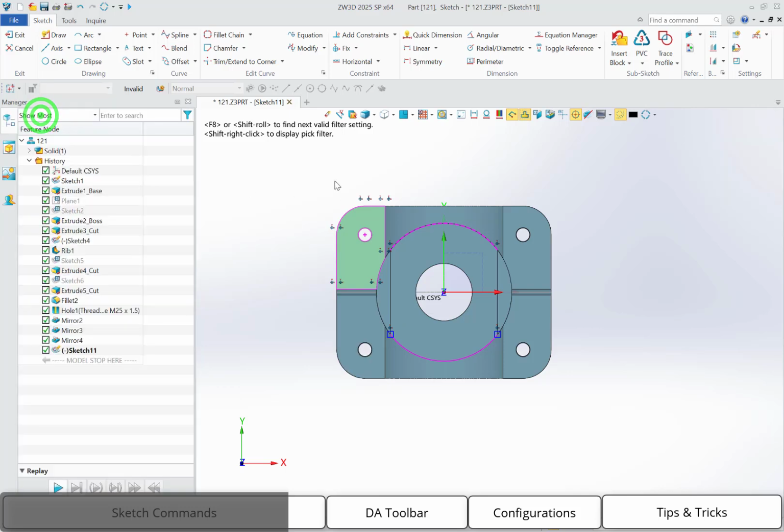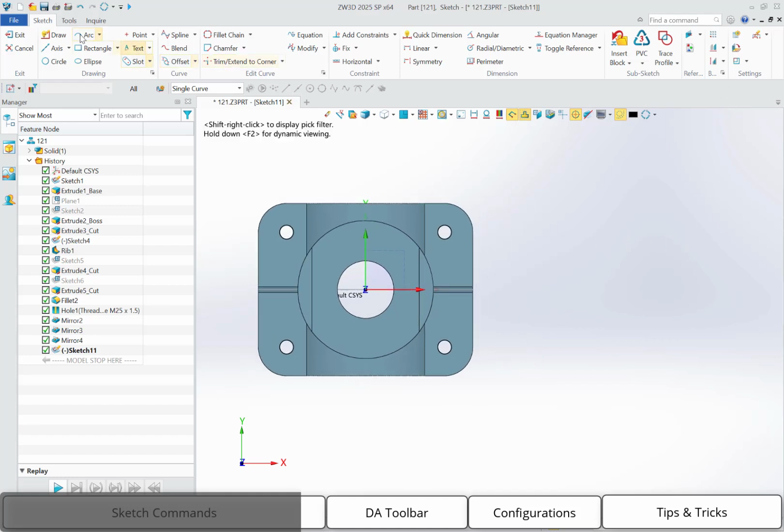And the last command I'm going to show you is overlap. So sometimes we have some overlap areas in our sketch. For example, if you copy the geometry from a DWG or DXF, sometimes there are some overlap entities. If you check manually by your eyes, it's very difficult. But with this command, it will be very easy.